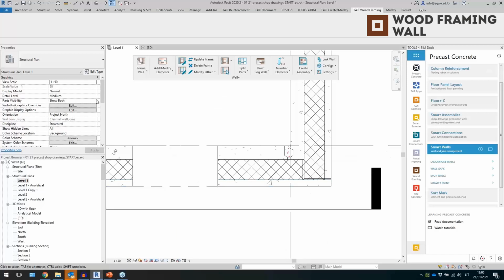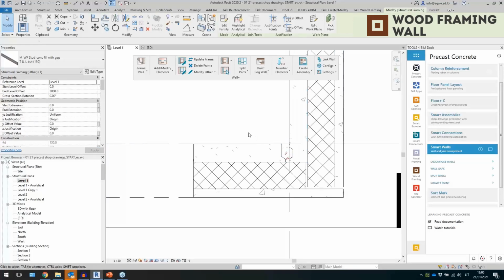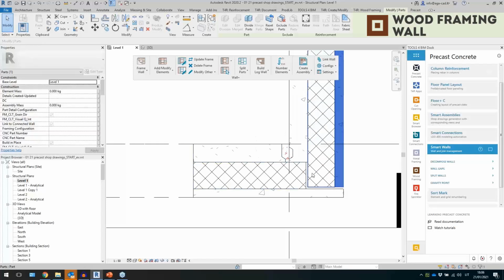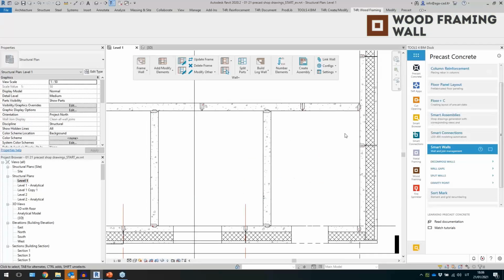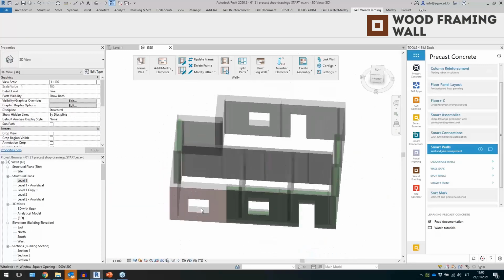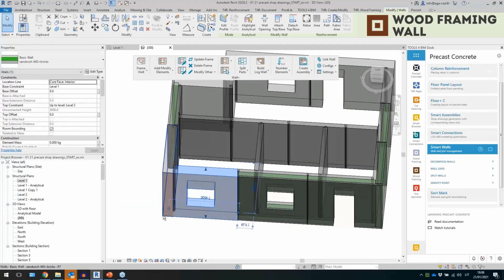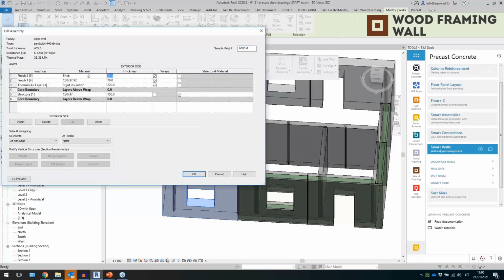And in this case, what I did here is that if we take a look, you see the tool automatically cut a part with these structural framing elements. As well, it made these extensions in the corners at the ends. So now I have these extensions, and also they are cut like that, right? So I had this kind of stuff created. So I think that's pretty good, but I didn't select these two walls because I wanted to show you they have an additional layer. These walls, they have an additional layer which I called brick.